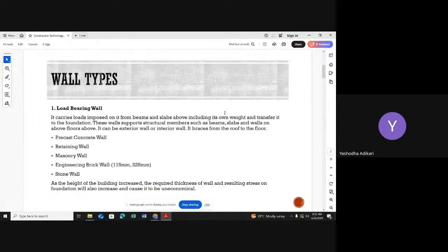When we cast a slab, we have to add water. Right? We have to add water to the slab, because the concrete should absorb enough water. If curing is not done properly, that's when sprinklers come in. In my last PowerPoint presentation, a wall should bear a very big load. Right? Going upward, we reduce the wall thickness. At the bottom, you should increase the wall thickness based on the building height.